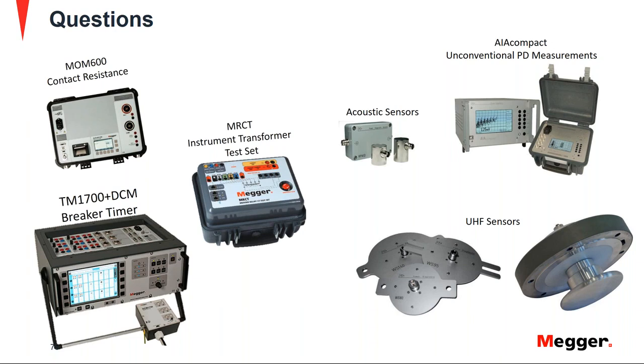Another method that wasn't really highlighted here is the acoustic method that would also help you in localizing partial discharge within your GIS. This was more on the measurement of the partial discharge itself, but you can also use acoustic methods to help localize the issue, but still using the UHF sensors, you have the ability to move those sensors, since they're either external or you have multiple embedded sensors. So as long as you're picking up a PD signal on one of your sensors, you would have an idea that the partial discharge source is in that section of your GIS.